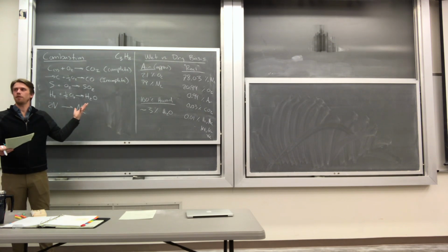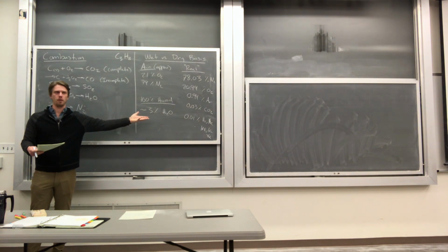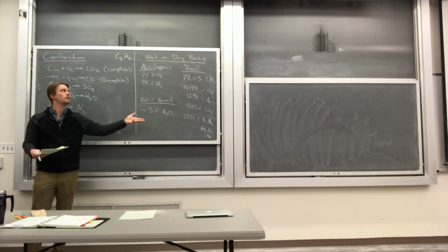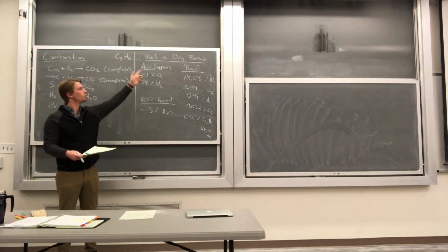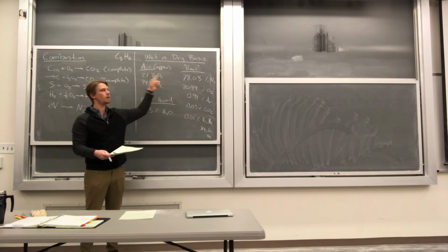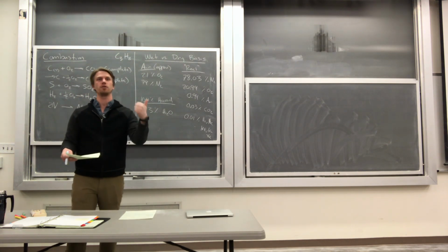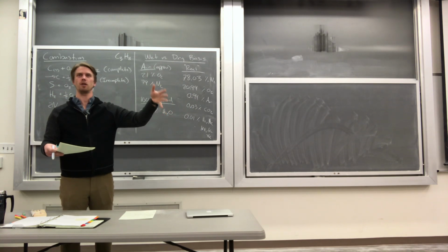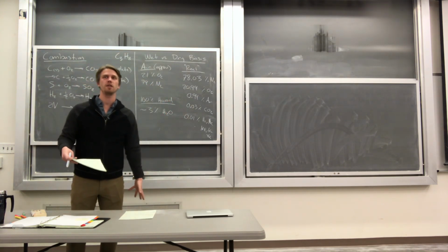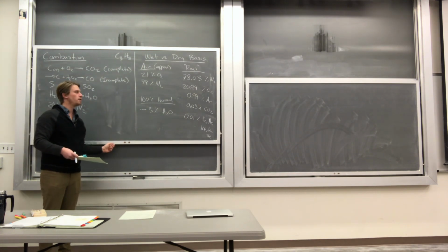And if you're burning a lot of fuel with a particular air-to-fuel ratio, the amount of water can mess things up a little bit. So there are a lot of reasons why we want to compare things on a wet and a dry basis. Wet is going to be the composition including the water. Dry is going to be without. All of these that I've written on the board are the dry basis for air. But based on whether you're in Salt Lake, Las Vegas, Phoenix, Houston, Charlotte, those are all going to have different relative humidities, and it may affect your air-to-fuel ratio.